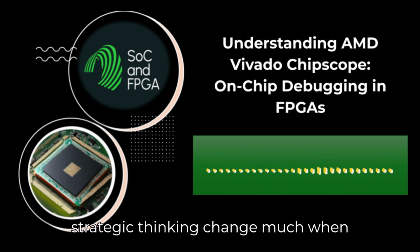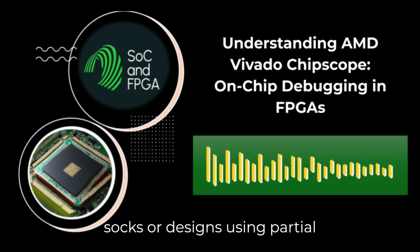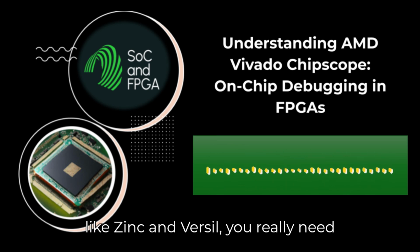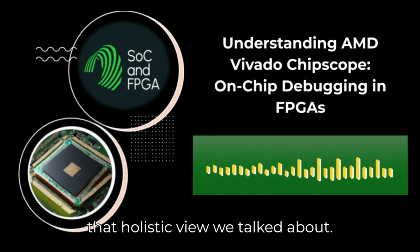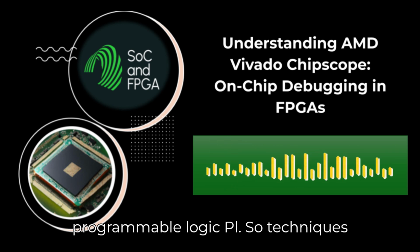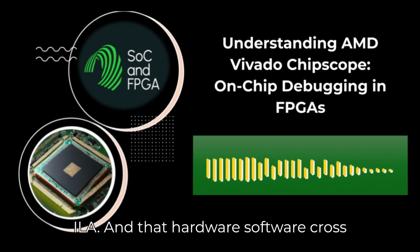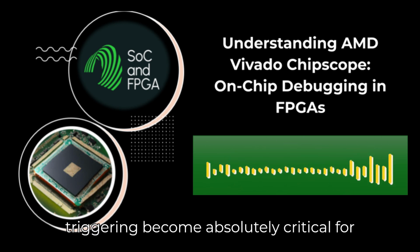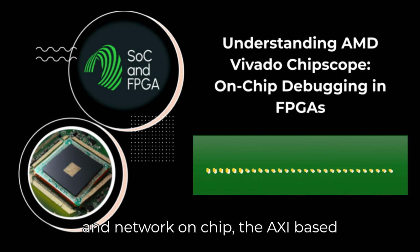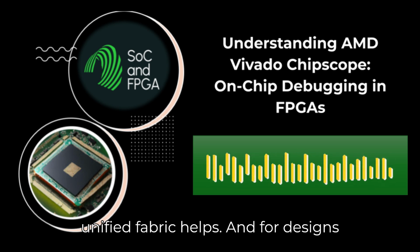And does this strategic thinking change much when you're dealing with really complex architectures, like those heterogeneous SoCs or designs using partial reconfiguration? It does require adapting the strategy. For heterogeneous SoCs like Zynq and Versal, you really need that holistic view we talked about. Debugging often involves interactions between the processor system, PS, and the programmable logic, PL. So techniques like AXI bus monitoring using the system ILA and that hardware-software cross-triggering become absolutely critical. For Versal specifically, with its AI engines and network on chip, the AXI-based debug fabric provides the necessary infrastructure to get visibility across all these different domains. Right, the unified fabric helps.